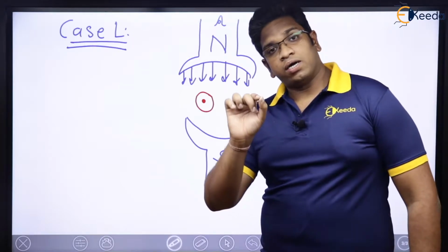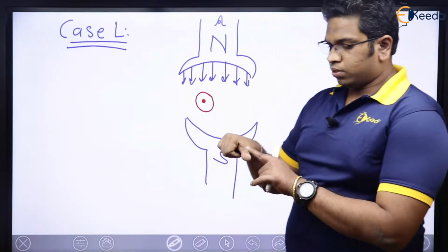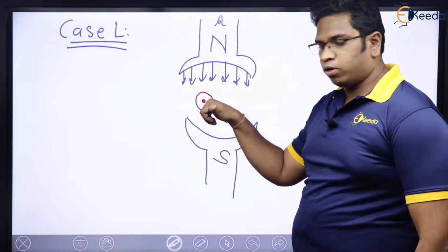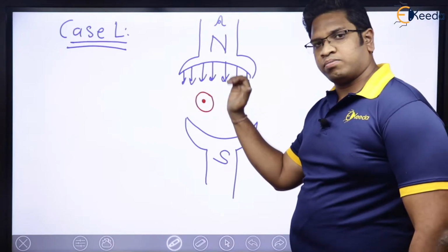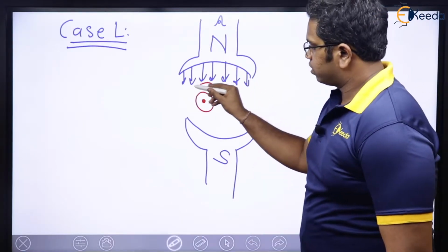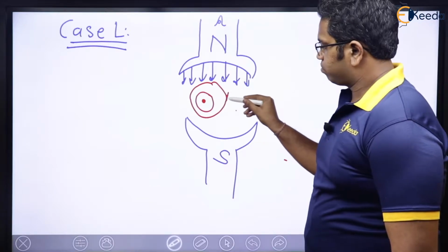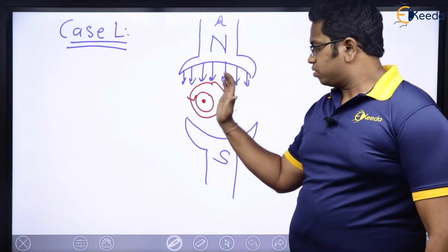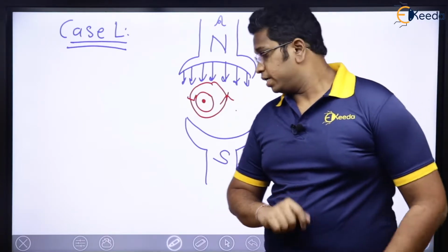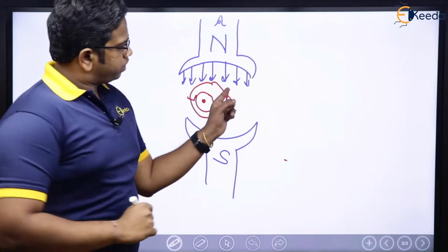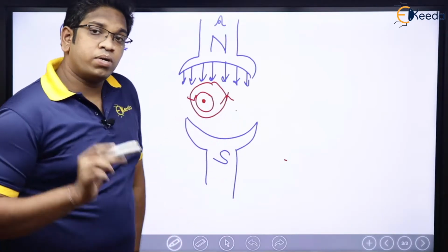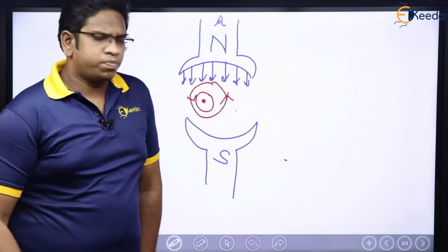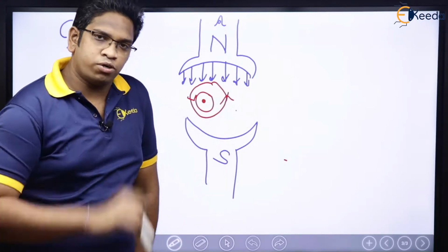The right hand thumb rule. So if this is my thumb, it is out of the board. So the current is out of the board, and the direction of flux will be like this, which means this is the direction of the flux. Outward current, this is the direction of flux, right? Now see here, what is happening here? This particular flux, which is nothing but the rotor flux, is getting opposed by the stator flux here, which means here the net flux will be 0.